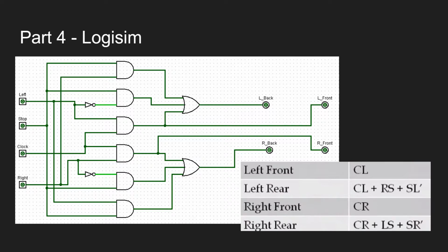Here we use Logisim to create a circuit that uses AND, OR, and NOT gates to output the correct outputs using these simplified equations. Here we've used 2 NOT gates, 6 AND gates, and 2 3-input OR gates. Now this is one way that it could be done, but this way can be expensive to make. So we will use this and convert it into a ROM circuit.